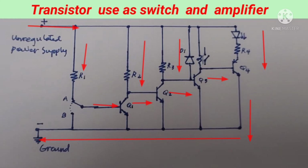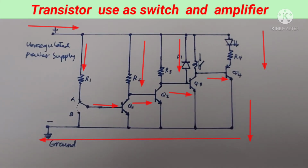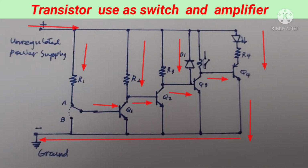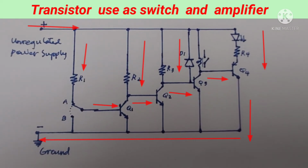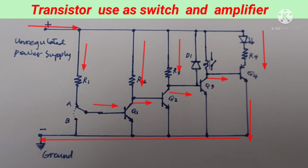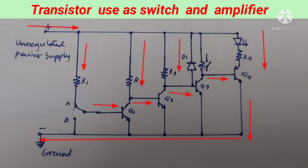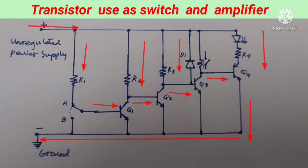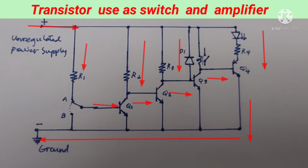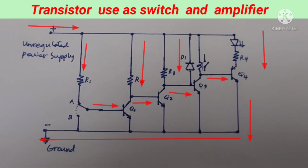The R3, the bias resistor, applies voltage to Q3. The Q3 will switch on, and the negative output of Q3 is applied to Q4. Q4 will saturate or switch on. The LED will light.